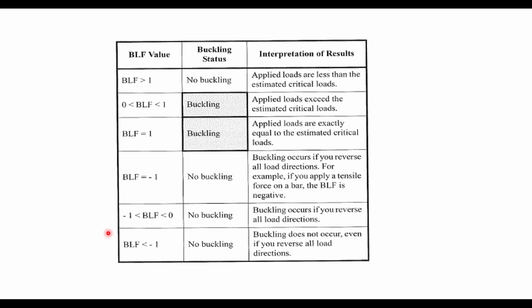This is very important. If you know this particular chart, you can understand the buckling results. The first thing is the buckling load factor. If it is greater than 1, your component will not buckle, because the applied loads are less than the estimated critical loads.